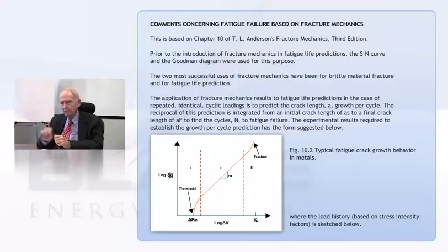So there's great expectations when you try to apply fatigue failure based on fracture mechanics. On this curve that says comments concerning fatigue failure based on fracture mechanics, there's a little curve there. It's a typical curve. It came from Anderson's book.